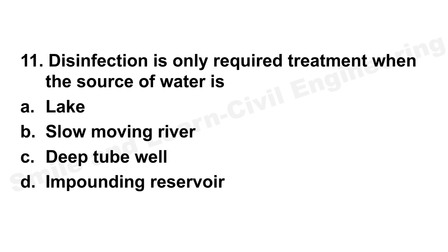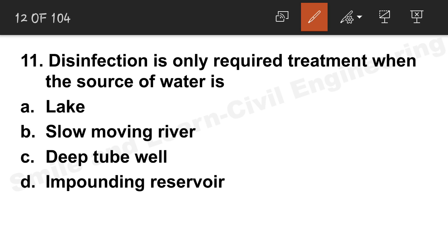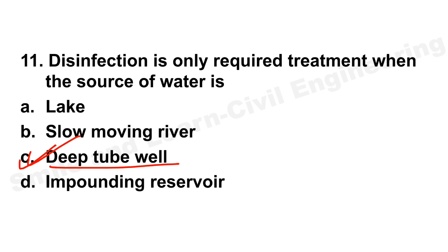Question number 11. Disinfection is the only required treatment when the source of water is. See, we don't require any other treatment like sedimentation or coagulation or filtration if the water is from a deep tube well. Since we are using a strainer, the water is already purified, but it may contain some waterborne bacteria which will cause waterborne disease, right? So disinfection needs to be done. So option C is the correct answer.